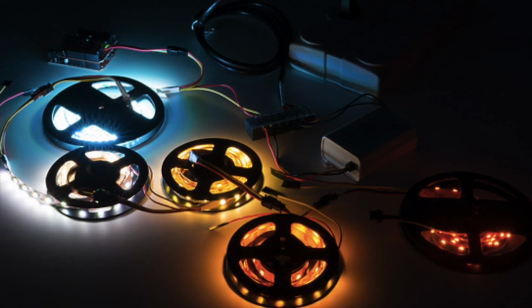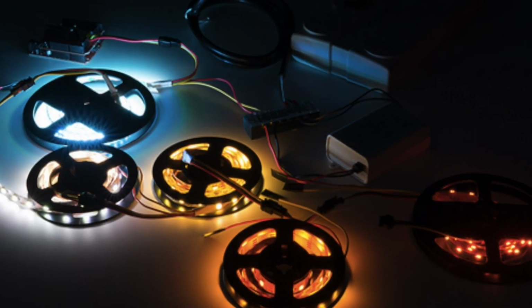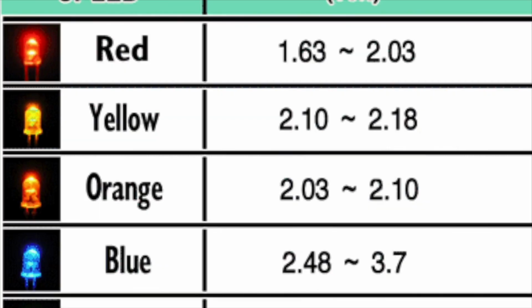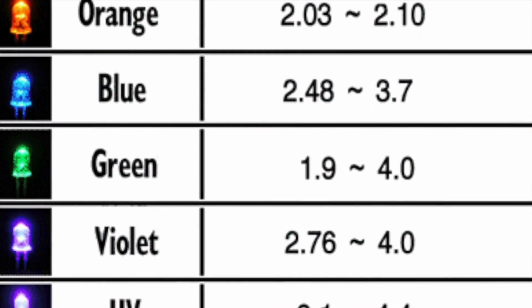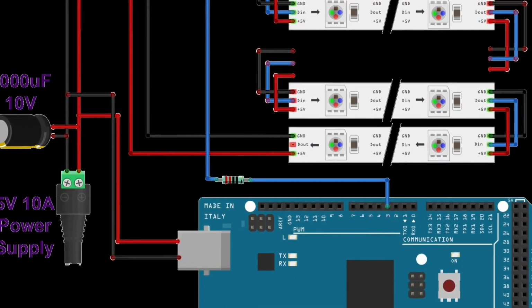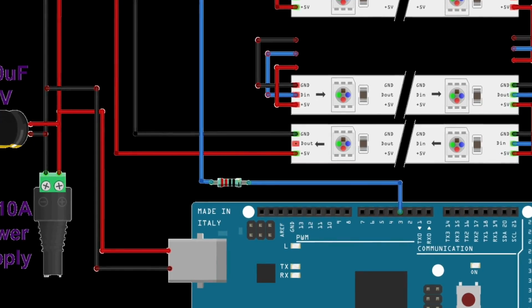Also, when RGB LEDs are not getting enough power, they tend to color shift. If this happens, you'll see the colors on the end of your strip shift towards red, since the red LED on the chip is the one that requires the least amount of power. The others brown out first. If you start to see power drop or color shift along your strip, you should add additional power to the end of the strip.